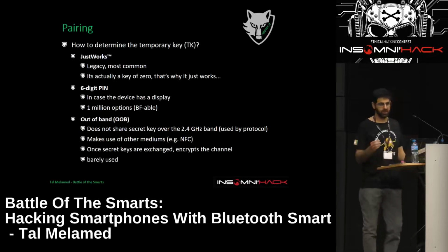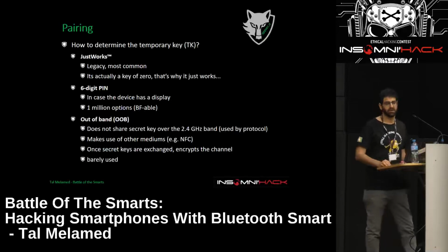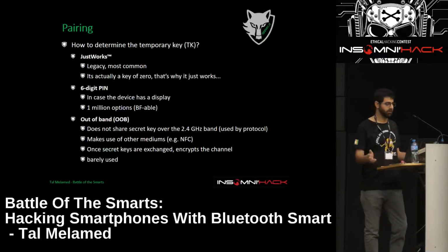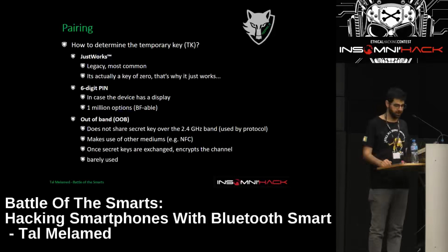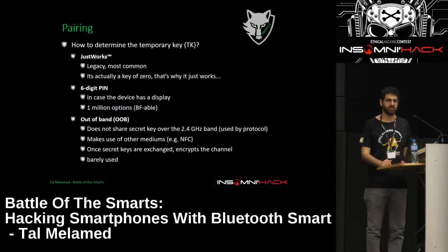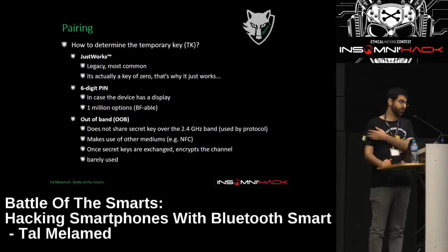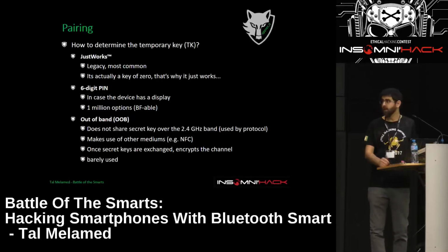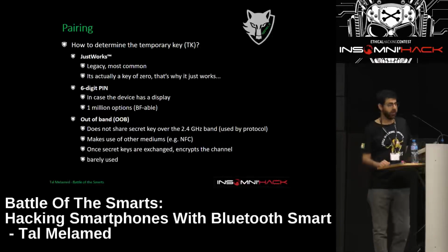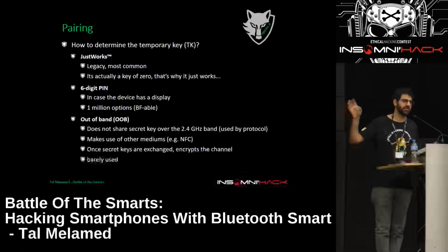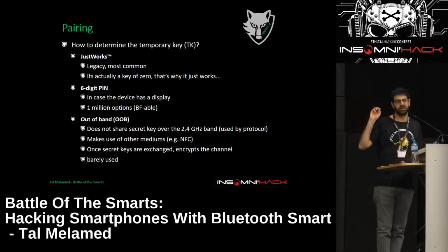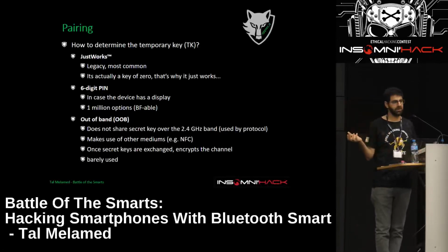There are 3 main pairing methods between the device and the application. The first one is Just Works. Great name. The fact that it just works is because the key is a bunch of zeros. It sounds funny, but I'd say about 90% of the devices use that.